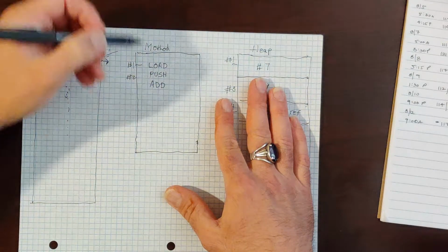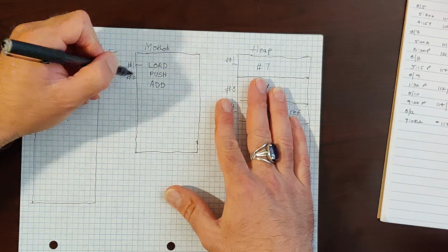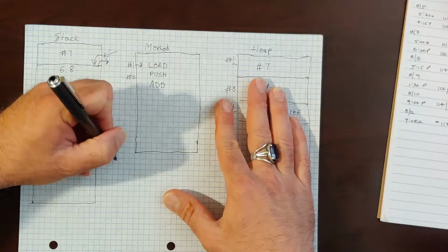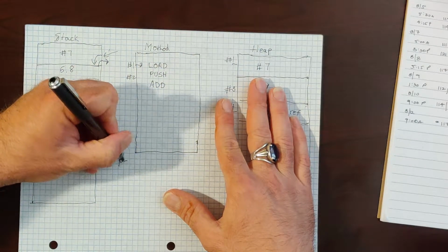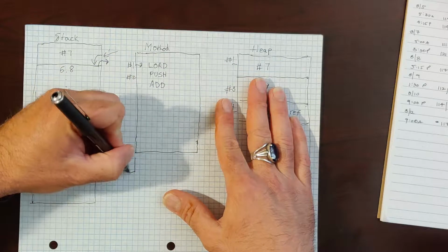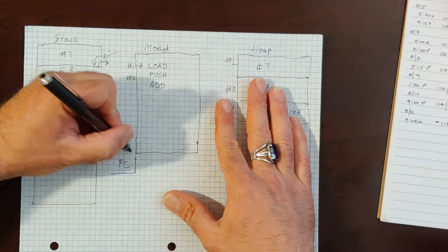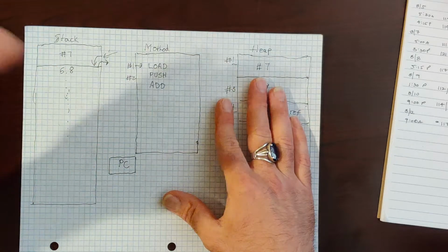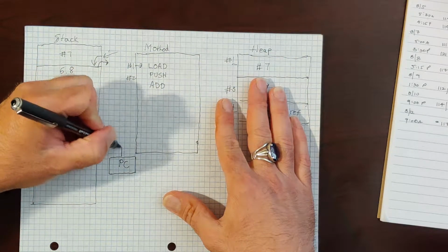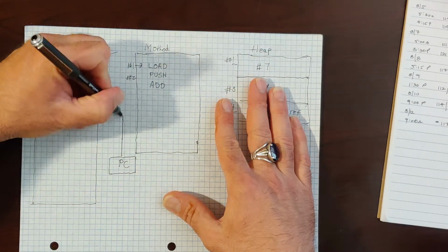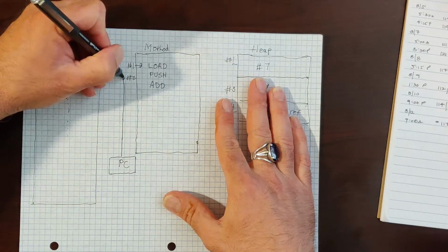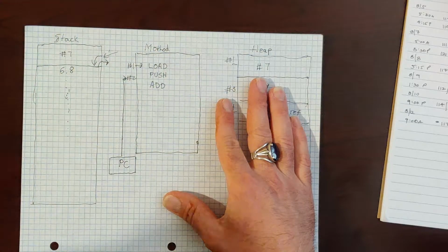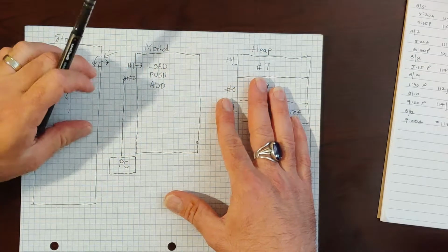And in order for the machine to keep track of where we are in the program, what instruction we're executing, we have a special register called the program counter. And this is exactly analogous to the program counter in an 8-bit CPU or really any kind of CPU. And this program counter simply has a counter that points us to the next instruction that we're about to execute.